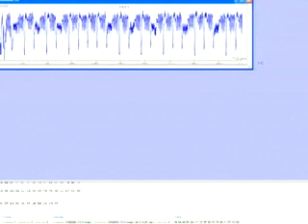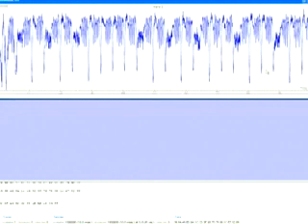Okay, so what do we see? Are you familiar with RSA implementations? Well, what you do in an RSA is an exponentiation. And for each bit in the exponent, you do a square operation. And if the bit is 1, you do an additional multiply. And what we see here is each peak downwards is the boundary between a square or a multiply. And then where that dark bit is, that's the multiply operation. So I don't have a pointer, but better just do it that way. That's easier. This one.